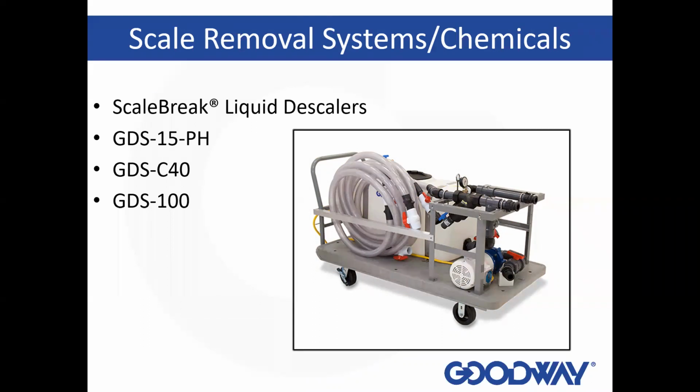You know, typically you want a good flow velocity. That's not to say that you can't do this statically. I've seen it done statically, where you fill the water side up with a descaler, and it does the job. But when you have flow velocity coming over the tubes, that enhances the descaling performance, so it's always good to have that. I think really what it's a function of is you have more force being applied, and you have turbulent flow commingled with the descalers happening at the same time to give you the best cleaning performance.